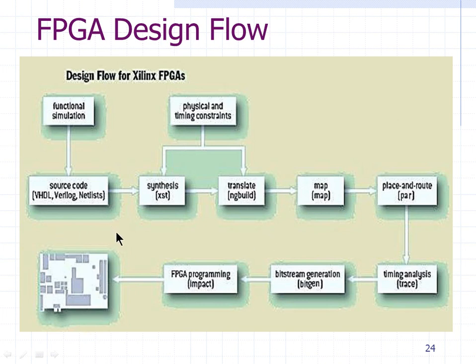Out of the entire cycle, around 60 to 65% of the time will be spent in design and verification. The other 30, 35, 40% of the time will be spent on the back-end activity. Synthesis onwards is called back-end activity. Synthesis is sometimes merged on both sides. It's called RTL synthesis on this side, and physical synthesis on this side. So it's partitioned, and half of it goes here, half of it goes here.